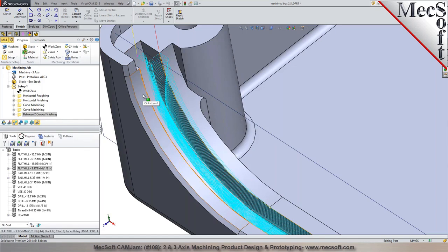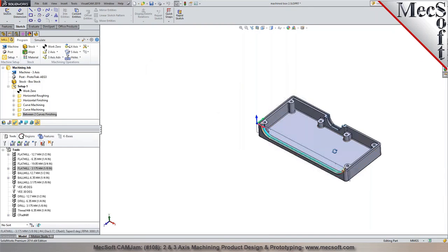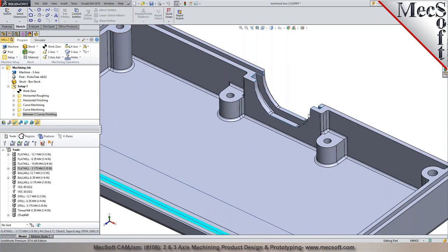So I just showed you if you just want to do a centerline pass, one cut to follow along it, I just had to create a sketch that goes on a center line, so I could drive the toolpath the way I would like it to. So the same thing can be applied over here.